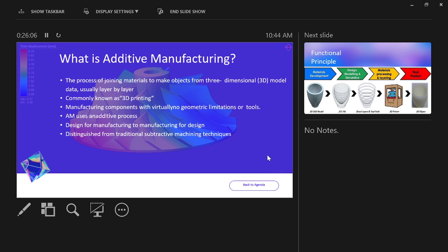Now there are different materials in this, for example the transparent one here, and then this software-based material. You can achieve this from software also, and in a single go you can print. So this is a multi-material advantage. So we have that J850 printer, that is a polyjet printer. From that you can achieve anything, or multicolors you can achieve from it. 5 lakh plus color combinations you can achieve by combining five different materials: black, white, then magenta, yellow, and cyan. So from that you can achieve any color.